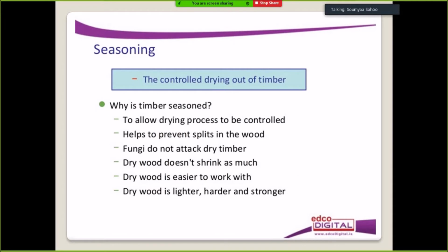Then next we shall discuss seasoning. Seasoning is the controlled drying out of timber. Why is timber seasoned? In order to allow the drying process to be controlled, it helps to prevent splits in the wood. It protects the dry timber from the attack of fungi. It prevents the dry wood from shrinkage, and dry wood is easier to work with. It makes the timber lighter, harder and stronger.